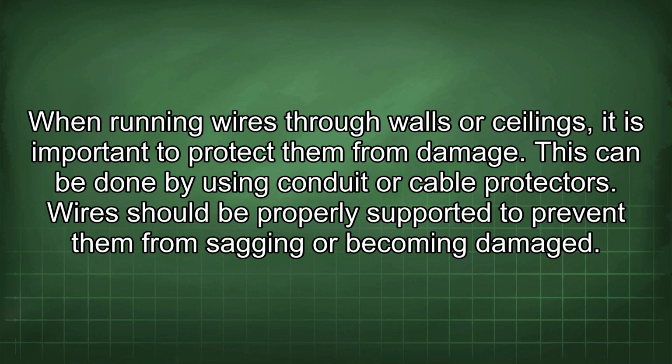When running wires through walls or ceilings, it is important to protect them from damage. This can be done by using conduit or cable protectors. Wires should be properly supported to prevent them from sagging or becoming damaged.